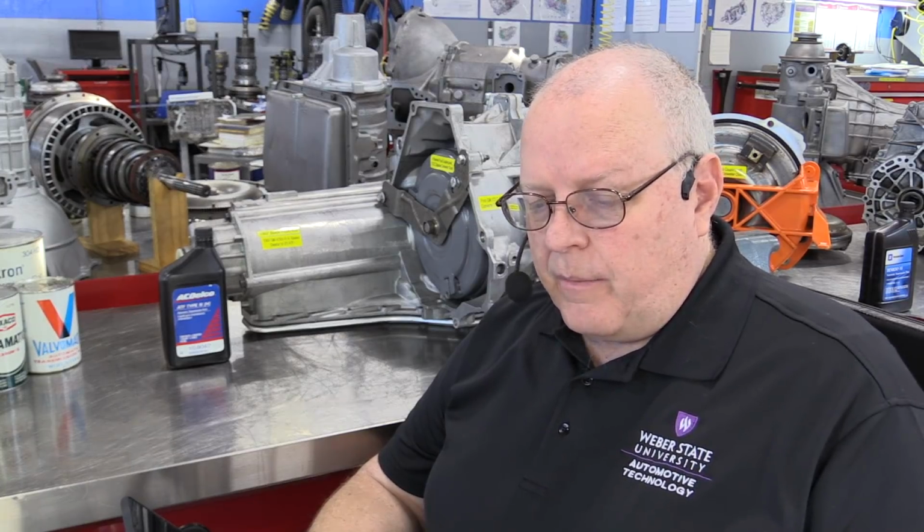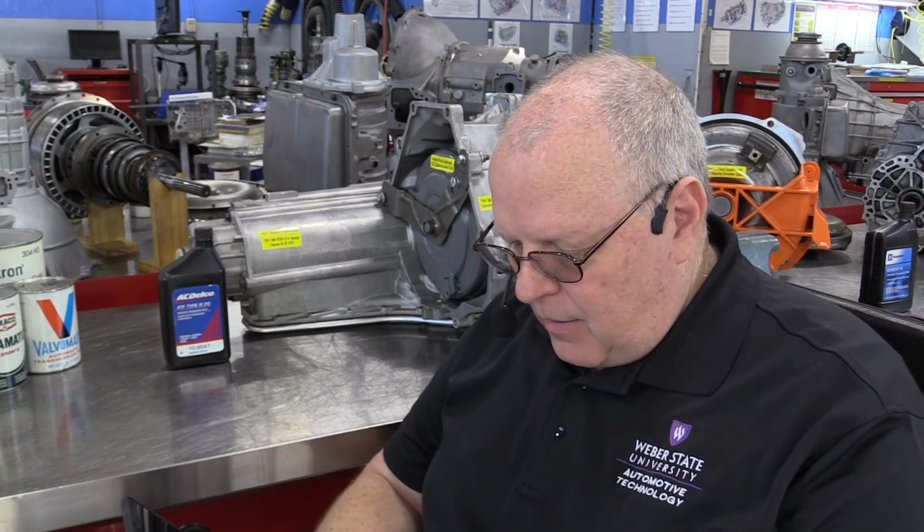For vehicles over 8,600 gross vehicle weight rating, change the fluid and filter every 50,000 miles. If the vehicle is not used mainly under any of these conditions, the fluid and filter do not require periodic changing for vehicles under 8,600 GVWR." So the service interval for Dexron III fluid is every 50,000 miles for a large majority of the drivers out there.